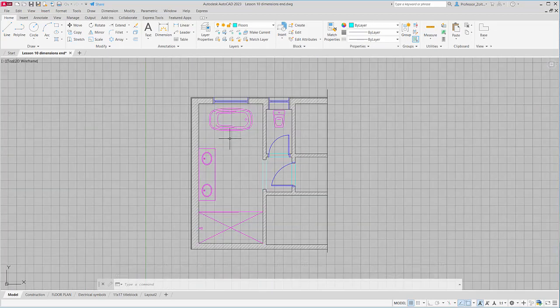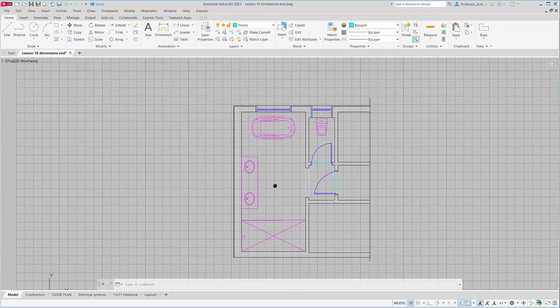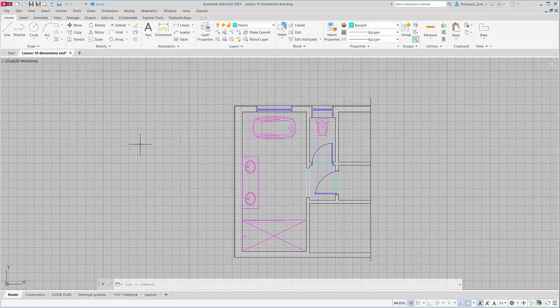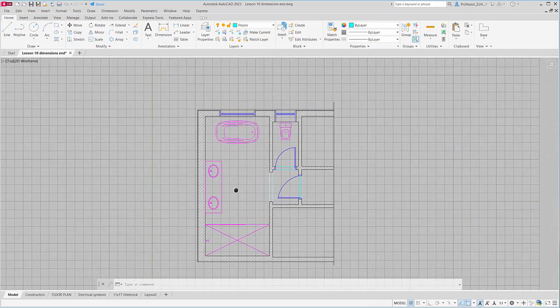So depending on the size of your tiles, you can lay them out so it fits on a grid here, or you can make the grid off, bring it in, and center it. Okay, let's say I want 2-foot by 2-foot tiles. You'll notice also I don't have any of these fixtures. Now I've got to be careful because I don't want a tile underneath here. I want a tile in the shower. So in the floor layer, I'm going to create a line here.